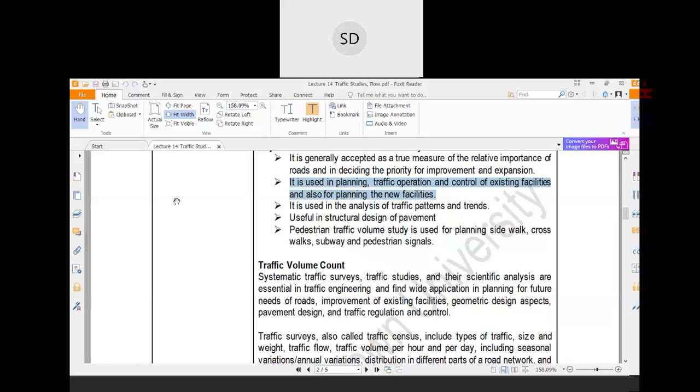Now if the number of vehicles is increasing, some traffic police can take control of that particular area. Now if the traffic volume is higher than in the previous case, you can go with a rotary intersection. Now if it is higher than what a rotary intersection requires, you can go for overbridges and underpasses.